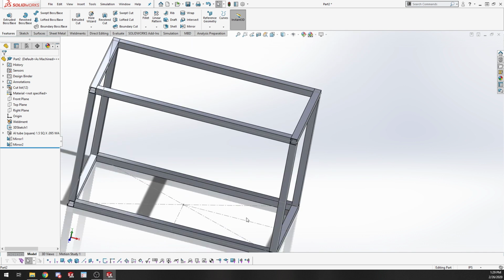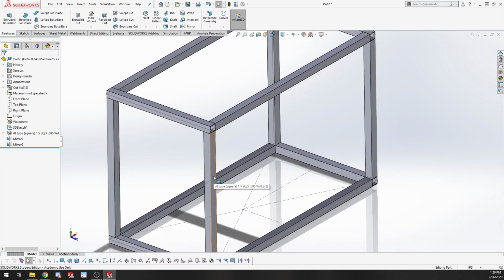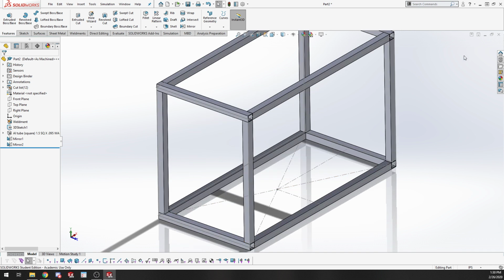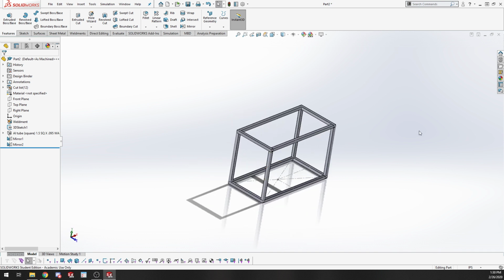In that case, I can do it. Otherwise, usually best practice is to make sure that you're setting up your sketches with the center line of your tubes. That's something like for chassis when we're designing a roll hoop and we have those bends. The bend radius is actually measured from the center line of the tube when you send it out to a manufacturer. So on that chassis we have 3-inch center line radii. So when we're making a roll hoop, we don't have to do all that extra math to offset the tube to keep it along the inside edge of a profile. But yes, that's the basics of 3D sketching. You can draw along different planes and stuff like that.